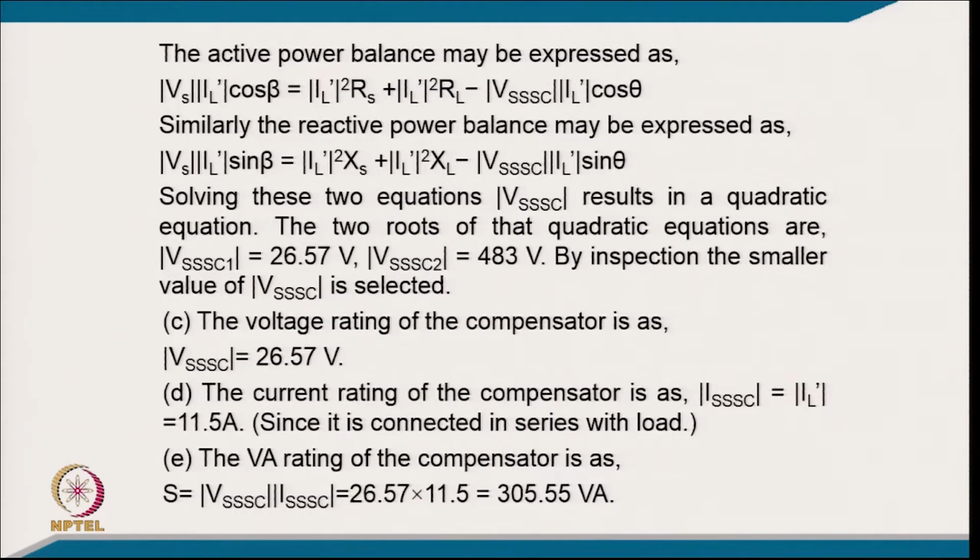The active power balance may be expressed as: the active power on the supply side equals the loss in source impedance, plus loss in load, minus the active power injected by the series compensator. Similarly, for reactive power, it is the reactive power consumed by source impedance, plus reactive power consumed by the load, minus the reactive power injected by the compensator.